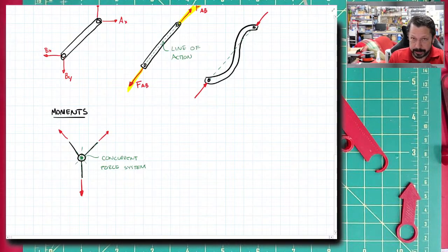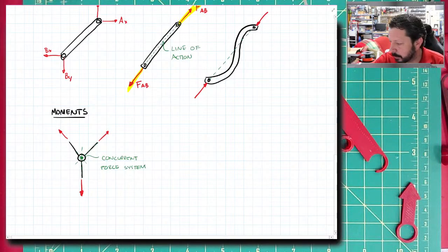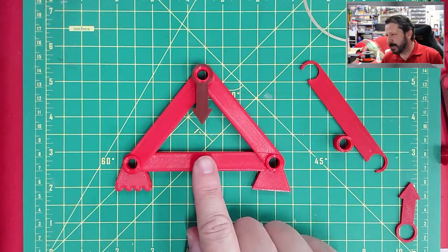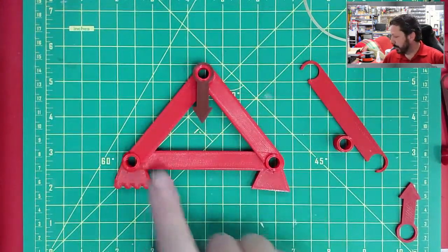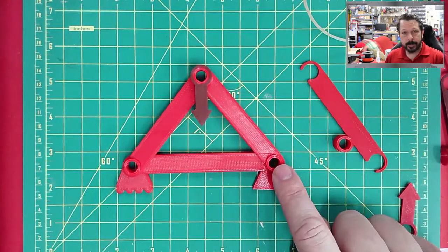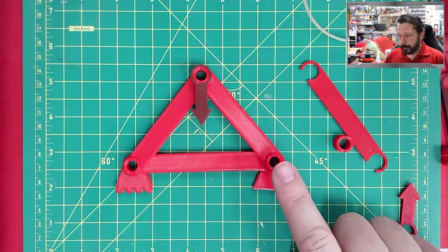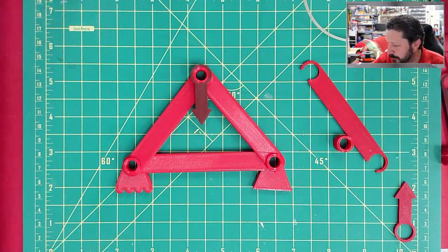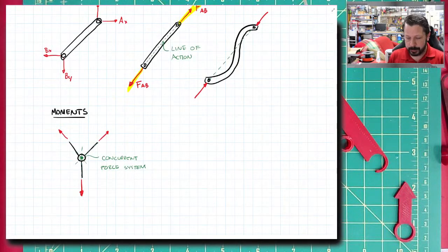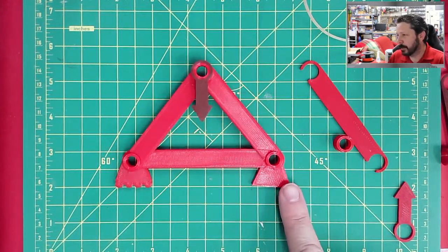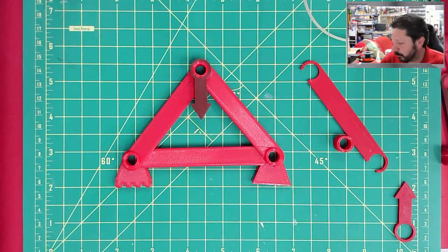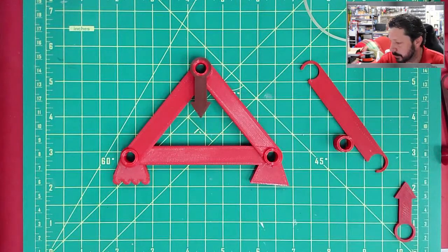Now, inside the truss, if we have each one of these be two force members, no matter how we arrange the truss, each joint is going to be a concurrent force system. But there's a little bit we have to do before we get to looking at each one of the truss pieces individually, because we don't know what's going on here at this reaction or here at this reaction. We need to do that first before we can necessarily look at all the little pieces.